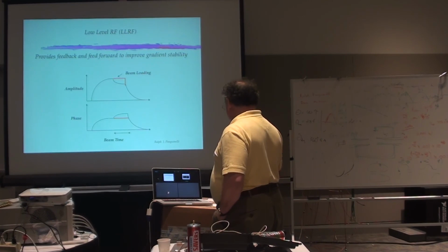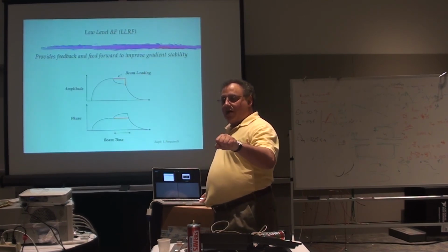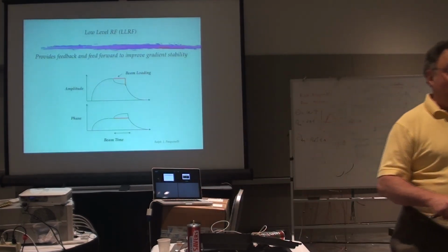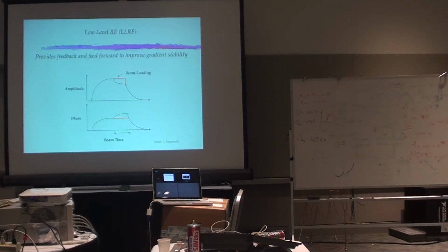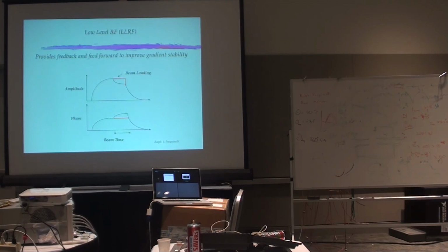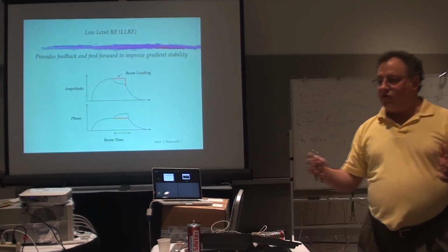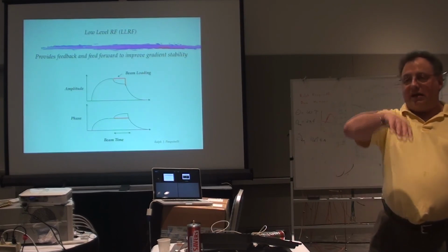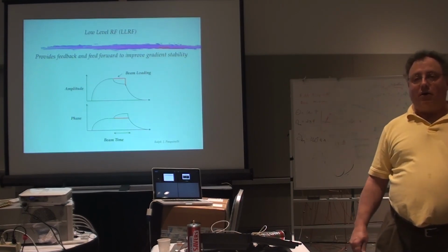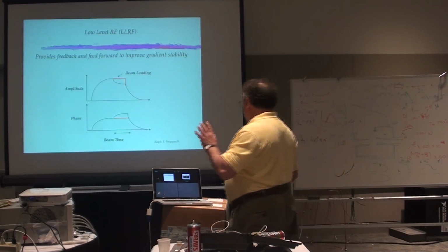And what it means is now you have to put more energy into the cavity than you were. So how am I going to pick that power source to do that? I do not want to be reaching gradient with saturated power, because now when the beam comes across, I've got nothing more to give. Okay? And I don't want to go to saturated power when I've got to give it more power. So that's a factor of almost 6 dB from where you get to the gradient in idling, and then when the beam shows up, I've got to put in 4 times the power in order to do it. And that's all dependent on beam current, of course. But if you don't do it, you will not have an energy flat beam.